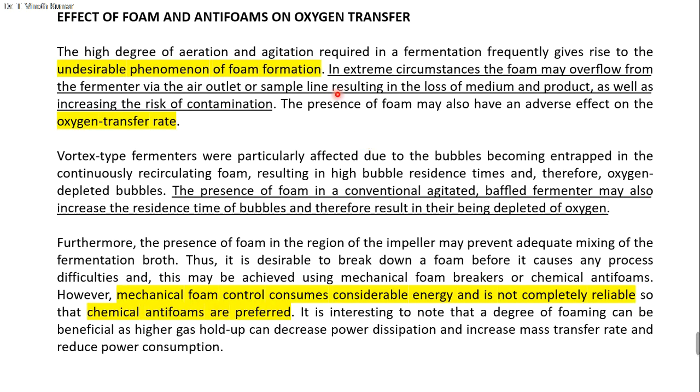Now coming to the effect of foam and antifoams on oxygen transfer. The high degree of aeration and agitation required in a fermentation frequently gives rise to an undesirable phenomenon called foam formation. Foam is a major threat for the production of proteins and enzymes, because the foam will denature the protein and the enzyme activity also. So we have to be very careful when dealing with the fermentation process for production of any type of proteins or enzymes.